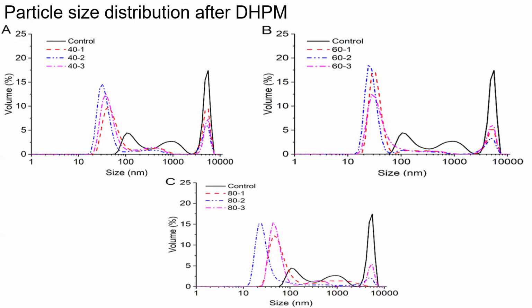And when they did the 80 megapascal treatment, again you see that this distribution becomes wider than 60 megapascal. That means even if we give a very high pressure treatment, it's not always successful. Even though the treatment is capable of creating smaller particles, they can come together once the sample stabilizes after taking it out from the microfluidizer. So again, the particle size goes up.